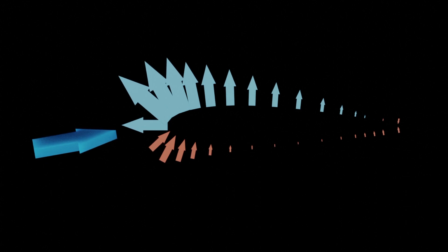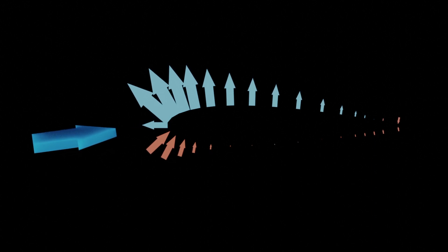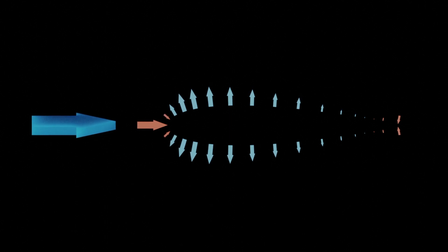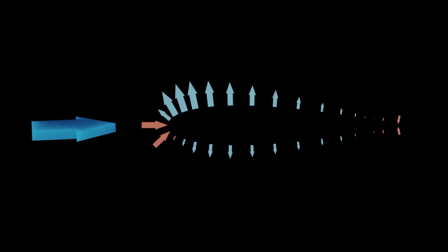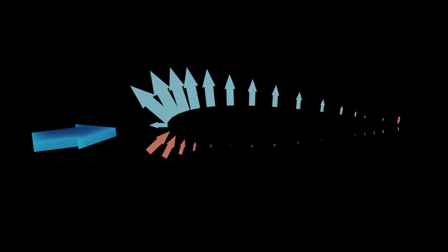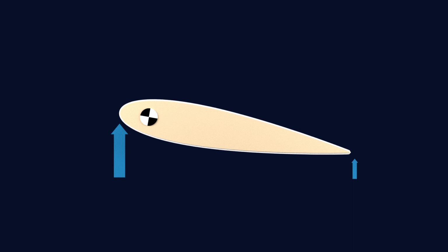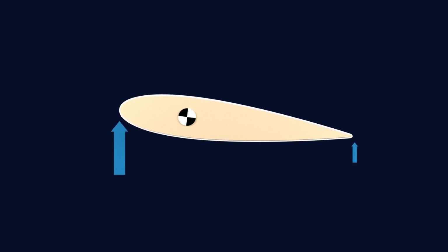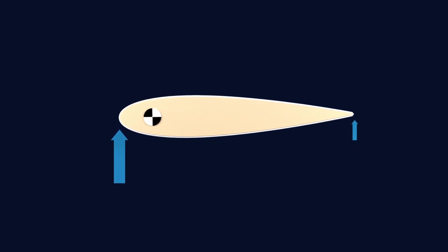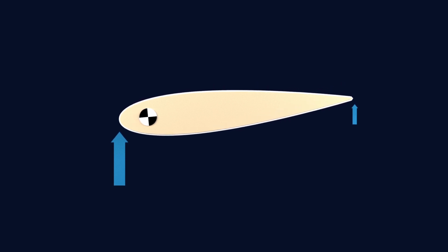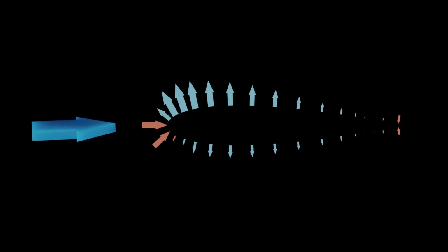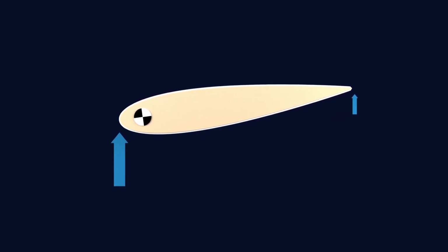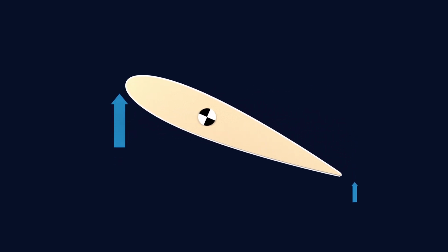The first thing to notice is that pressures are very unevenly distributed over the span of the foil. This is particularly relevant for the design of a balanced rudder like this one. For this design, the goal is that the turning forces or torque about the shaft almost cancel out, making steering effortless. For stability and safety, the designer usually leaves a small amount of resultant torque opposing the turn to automatically restore the neutral position. As the forces are so unevenly distributed, the shaft must be placed close to the fore end of the rudder to achieve balance.